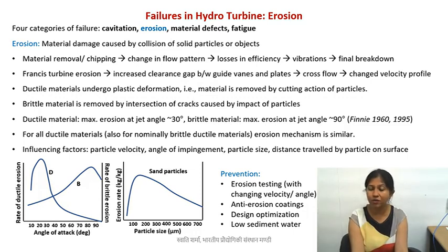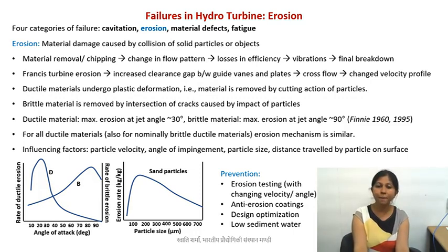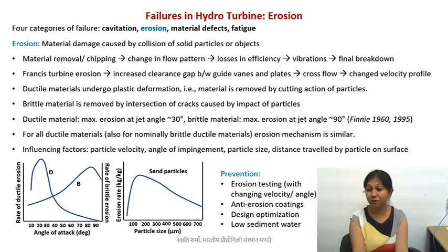However, one more thing that you can do is attach a filter where at least the larger particles are removed, and also, if it is suitable to the flow of water, you can try to remove the particles that are in the size range that is most damaging to your turbine blade surface. Okay.